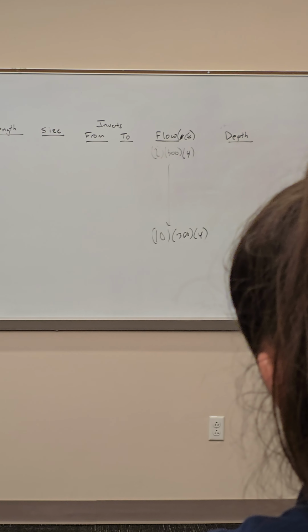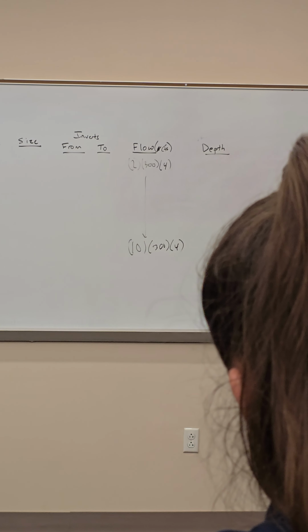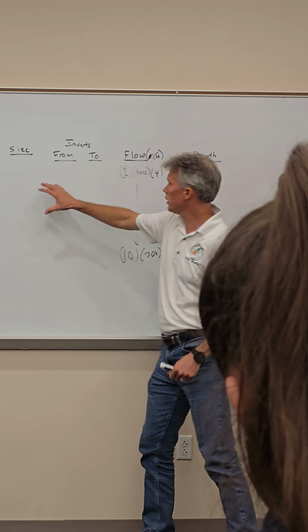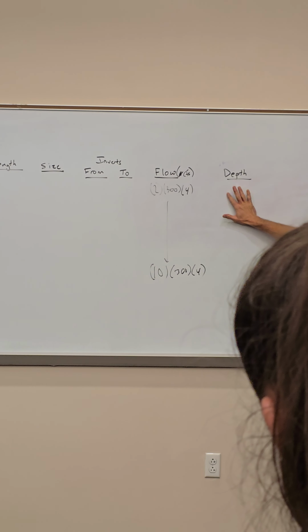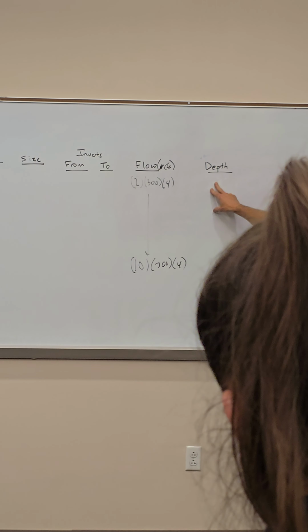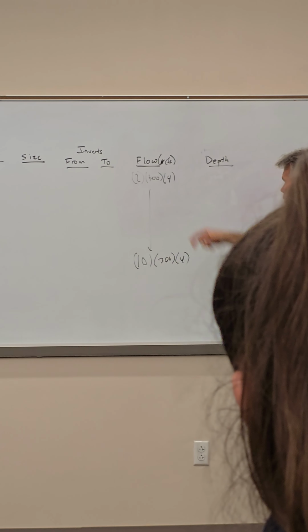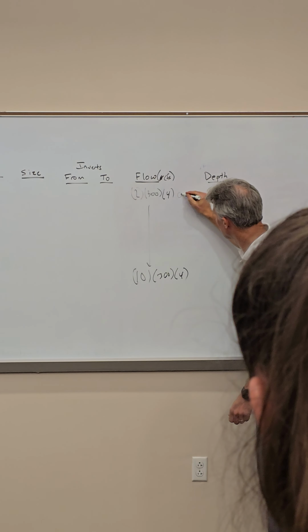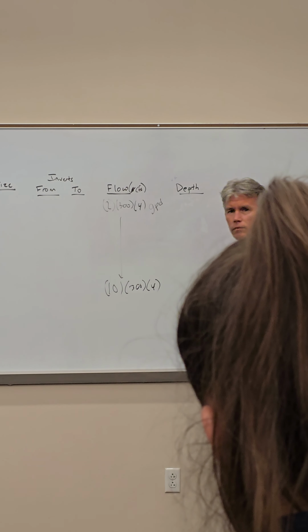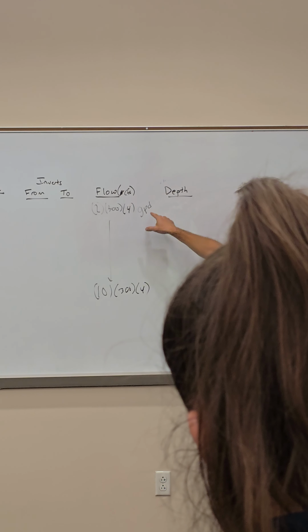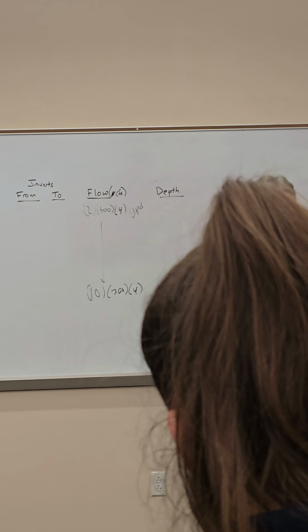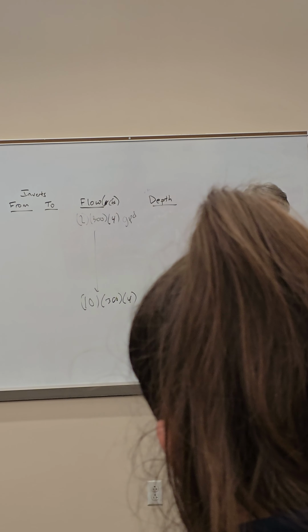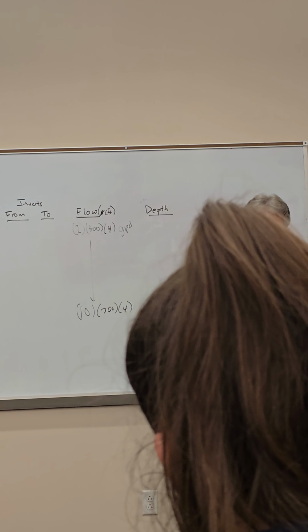Yes. That has to be changed to cubic feet, right? Needs to be changed to cubic feet per second. Okay. Because we're gonna use Flowmaster to calculate our depth. I'll show you how to do that in a minute, but yes, because these are in gallons per day. So when you convert gallons per day to cubic feet per second, it's gonna be a small number. Okay? It's gonna be very small.